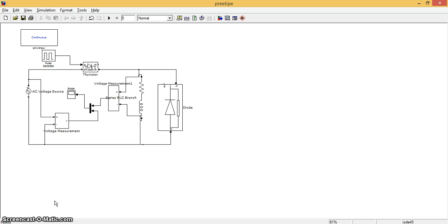This is a basic one. It only conducts in the positive half cycle because you can see that there is only one path for the flow of current. The ripple voltage contains high harmonics. For such harmonics, the current drawn by the load inductor will be less. Since the output voltage should not be rich in harmonics, this kind of controlled rectifier is practically seldom used.